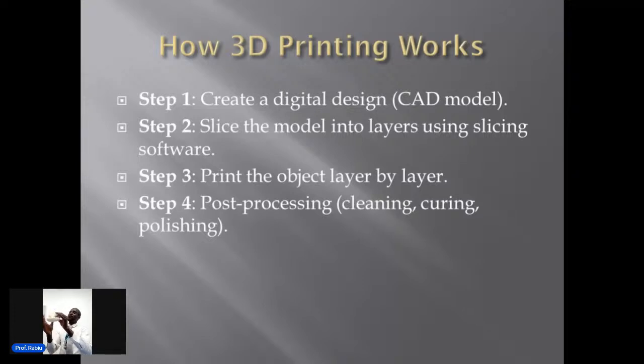When the light goes back, we try to continue, but this thing already moved. We try to hold it and do anything. It's not doing what we are expecting, so we have to give up because some of the layers are already missing. So there is no way it will continue from here. You get the point? So that is the problem. You have to also consider that. Make sure that your power is uninterrupted during the printing.